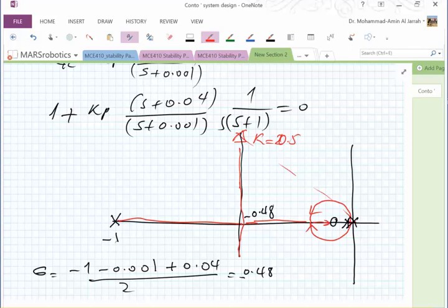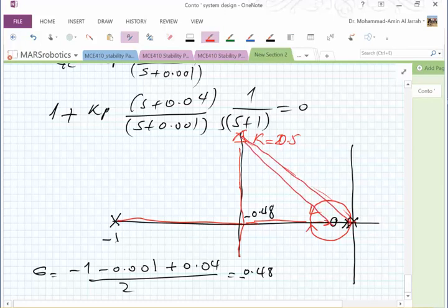And for a lag controller, what is the phase angle? There is a phase angle difference. Is the phase angle positive or negative? By the controller alone, the phase angle is the angle of the zero minus the angle of the pole. Which angle is bigger? The pole. So the difference in the angle is negative. Any controller whose phase angle is negative is called a lag controller, meaning that the pole comes before the zero. The pole always comes before the zero. It will have a negative net phase anywhere in the S-plane. But we make the minimum phase difference at the desired location. This is the idea. The key is to make the minimum phase difference at the desired location.